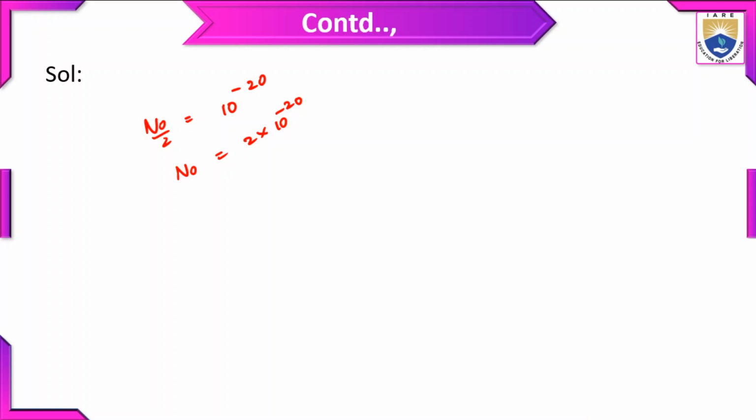Okay. So substituting the values of E_b and N0 in the expression of P_e. What is P_e? Probability of error. So probability of error is 1 by 2 erfc of square root of E_b, 0.25 into 10 power minus 8 divided by 2 N0.